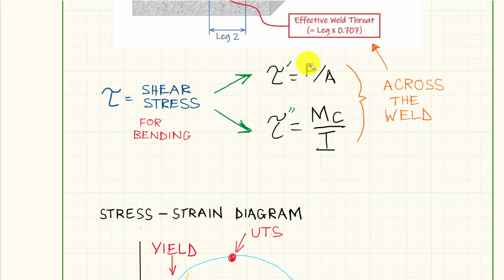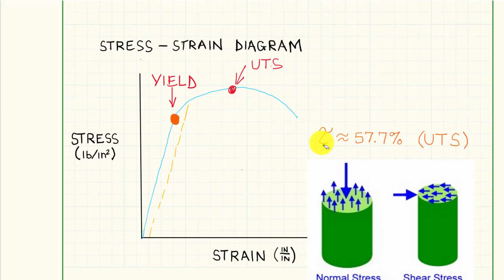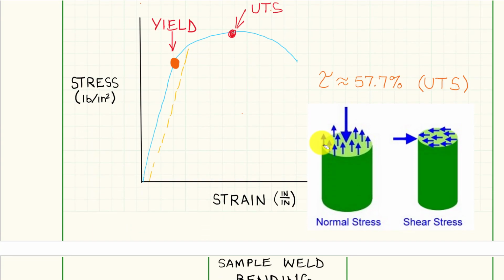And we can put that in here, put our force on there. We got primary stress, pretty easy. Secondary stress, we need to calculate the M, the max moment, our C, the distance from the neutral axis, and then our I value.